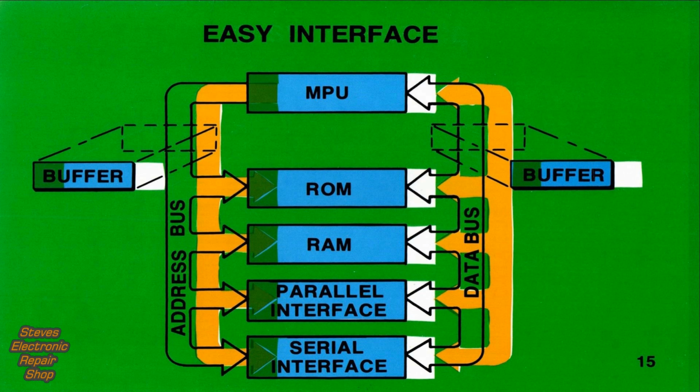Interfacing with the outside world is a major problem, no matter which microprocessor you select. Therefore, as a designer, you don't want to be bothered by bus interfacing problems inside the system, like having to buffer the address and data buses. There's strength in the microprocessor family, since these chips can usually be connected directly without additional buffering. Also look for TTL compatible voltage levels.